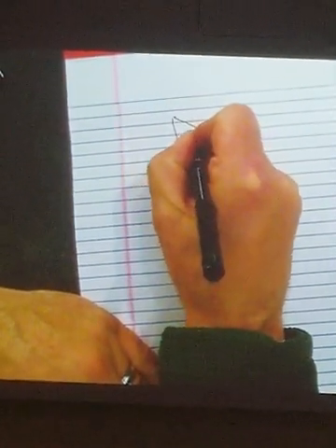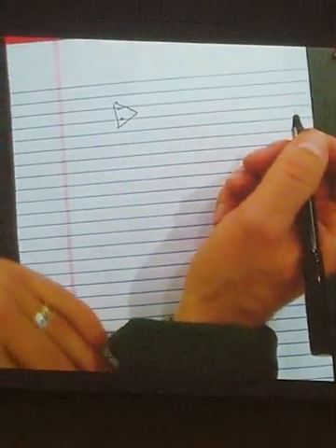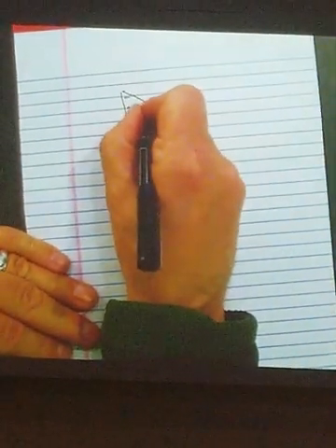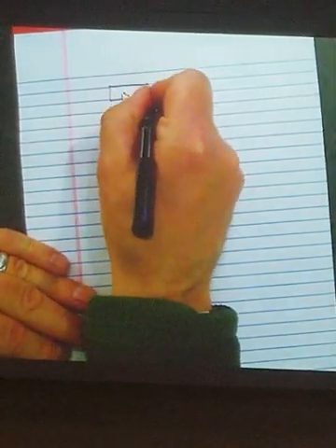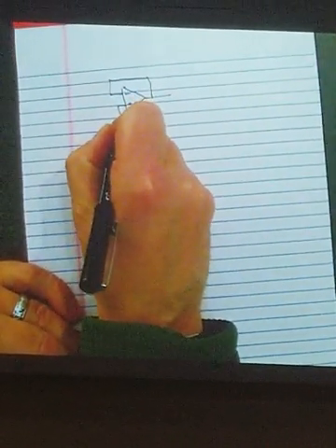But since we're talking about op amps, let's think about an op amp here, our 741. And just for the heck of it, let's connect it as a follower. So let's simply short the output back to the inverting terminal, and then let's ground the non-inverting input.